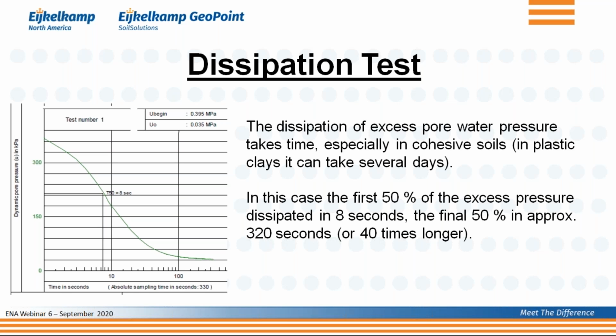So it basically means that this test lasts long, but the first part goes relatively fast, a lot faster than the second part, which is not a surprise, because you don't have more driving force to push the water out of the soil.